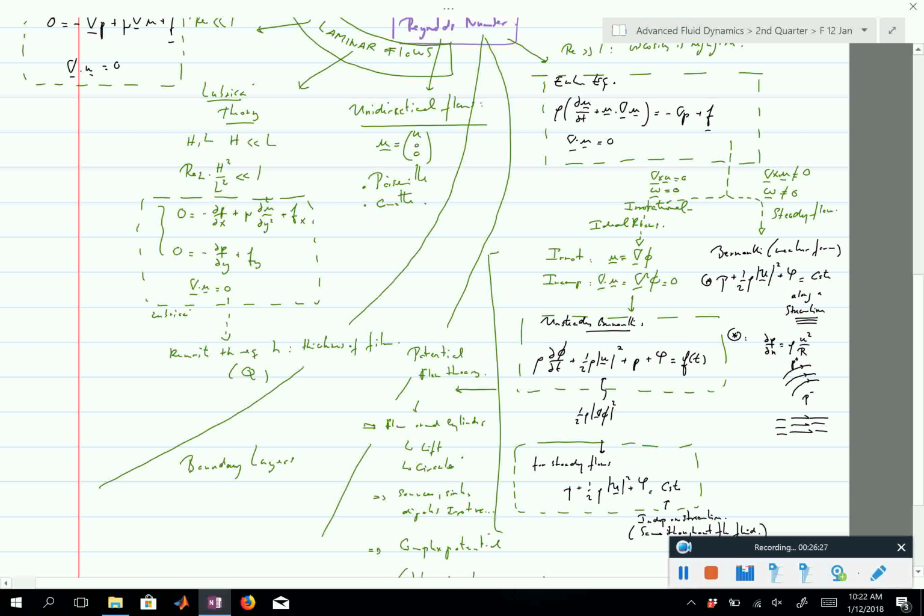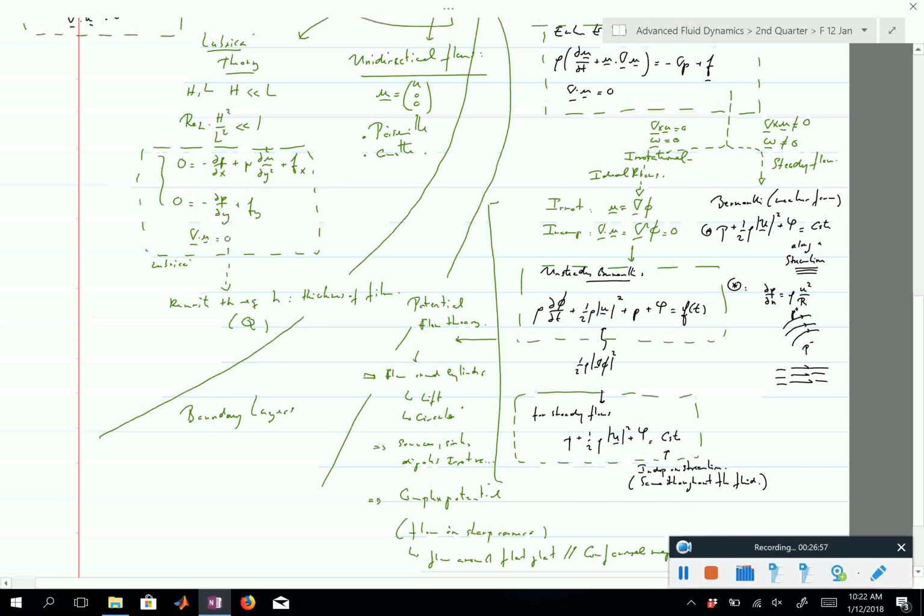So they're really at the interface between these cases. Just think about the flow on a flat plate, where both effects are important and both meet each other. The effect of viscosity allows you to impose a no-slip boundary condition, meeting the outer layer where you can assume the flow to be inviscid and inertially dominated. So we derived the equations for boundary layers, which are the following.